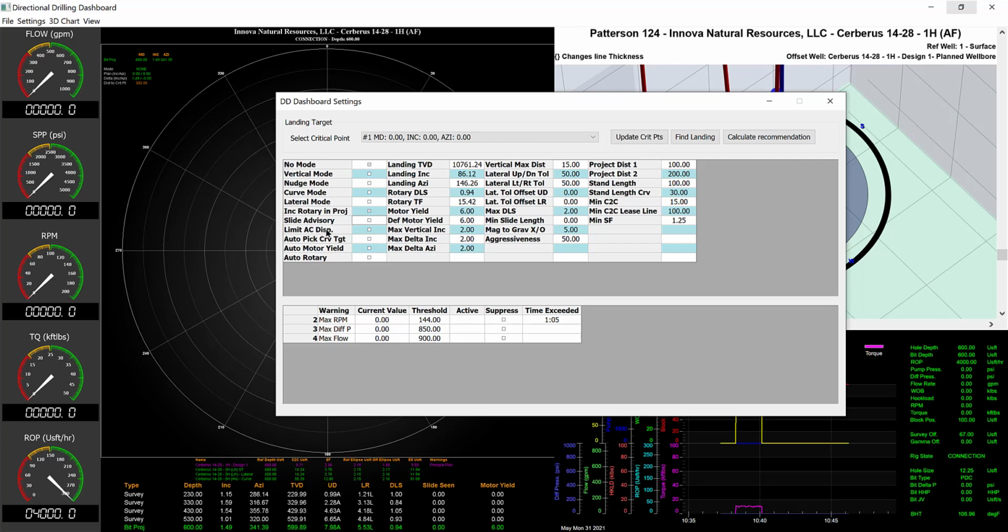Limit anti-collision display. Down here we've got our anti-collision display, and right now we can see 3 offset wells and our plan. We can see 2 of our offset wells are very close centre to centre distance wise, and one of them is reasonably far away, 55 foot.